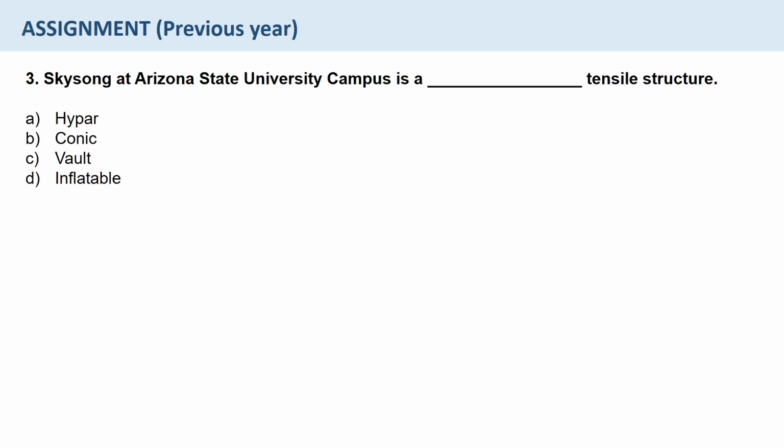Depending on the spans, a barrel vault system can be a cost-effective way to incorporate the tensile membrane on a project due to the repetitive nature of the design and efficiencies of manufacturing. Inflatable structure. Most commonly used as biodomes and for users to set up a temporary exhibition hall using pneumatic air inflating method.